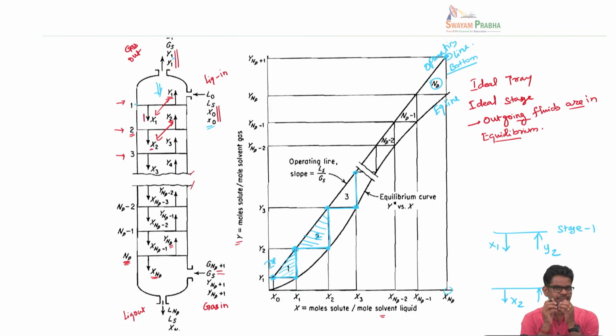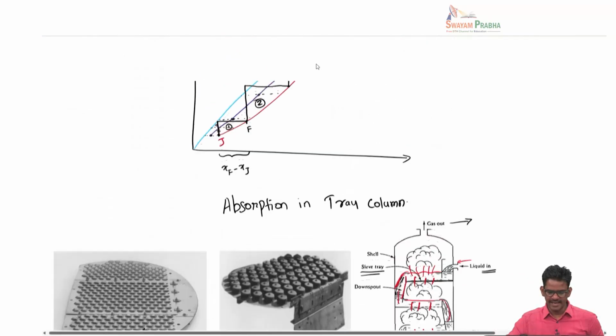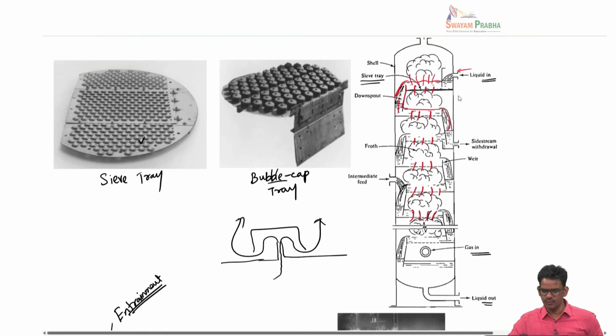Like I said, the actual design has provisions that maintain a particular liquid column in each tray. You can see there is a leveling here, so as to let only the overflowing liquid out. There is a small weir here that keeps a particular liquid height maintained.